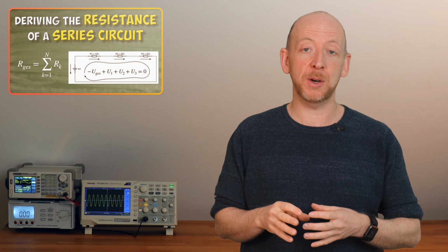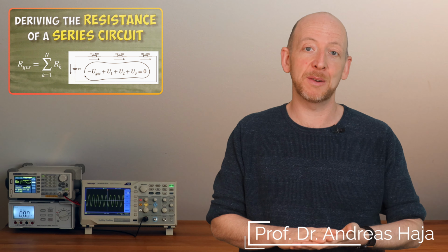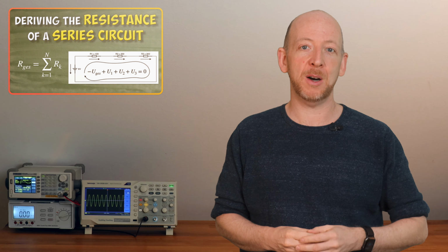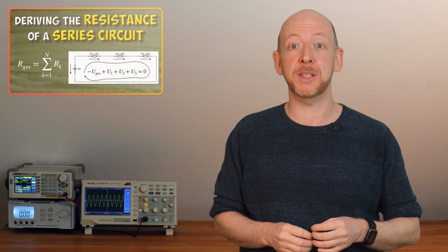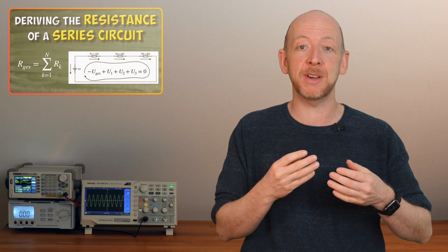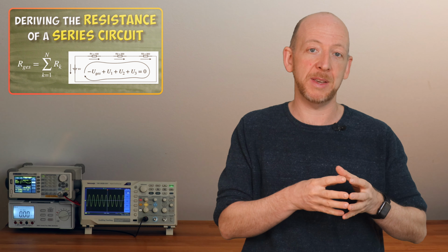In this video you will learn how to derive the formula for the series connection of resistors based on Kirchhoff's second law, the famous loop rule, and also based on Ohm's law. And you will learn here how to exploit the current equality in an unbranched part of a circuit and how the length and the cross-sectional area of a resistor influences the amount of resistance caused by a series connection.